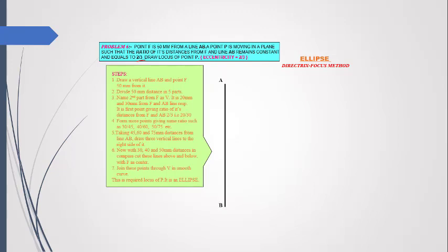Here this is the constant line, and this line is known as a directrix. From the AB line, draw a perpendicular line. Draw a fixed point on that line, that is 50 millimeter away from the directrix. Now divide the line in 5 equal parts. You can see here that I have divided the line in 5 equal parts, 1, 2, 3, 4, 5.